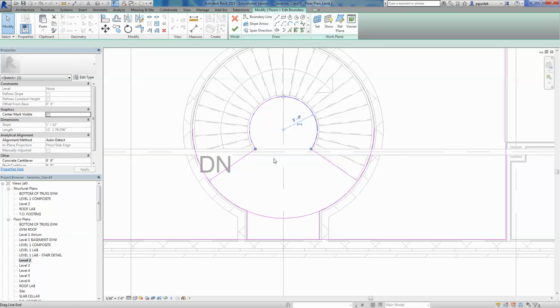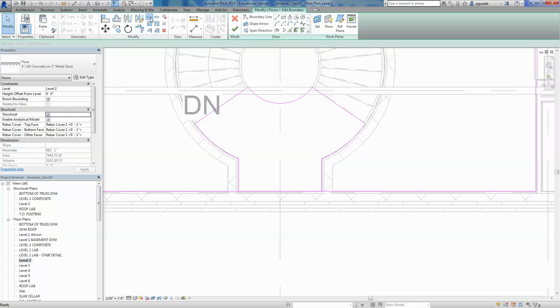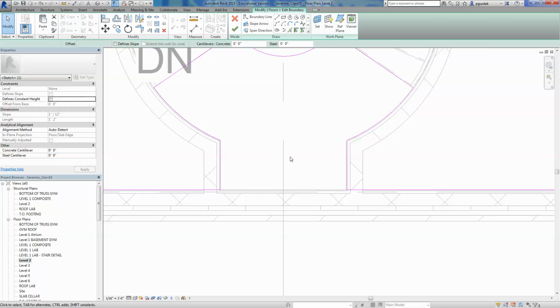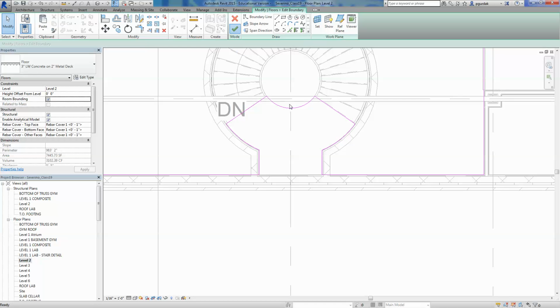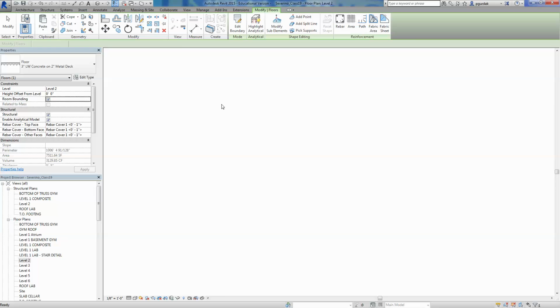Now sometimes you have to continue one of them and split, for example. Or actually no, I think you can trim here and here. And now you need to split in the middle though, to trim here, here, here, and here. And now you need to split again, escape over there, trim, trim. Now I left this piece, I shouldn't have split it there. You can say okay. It's going to ask me if you want the walls to go up. No. Let's go to the 3D.